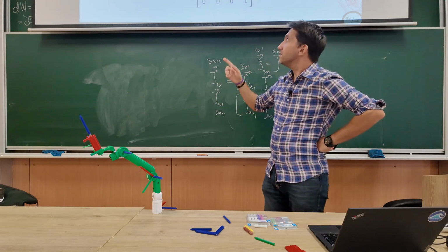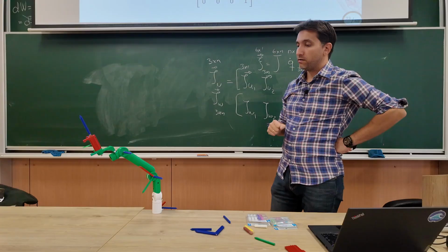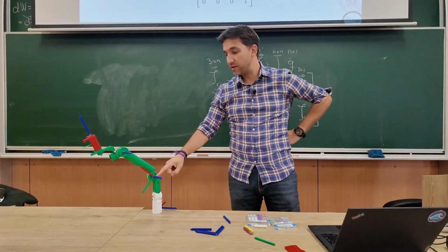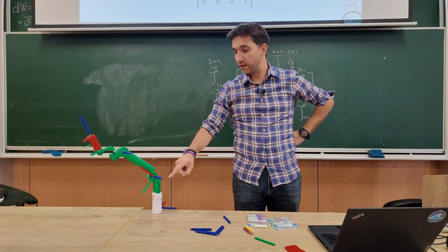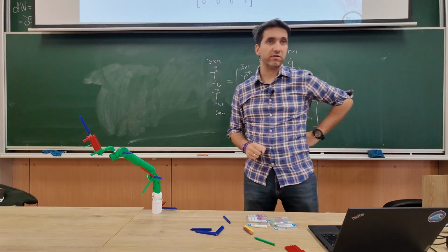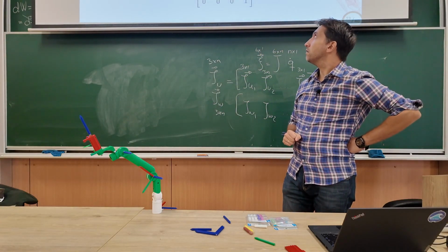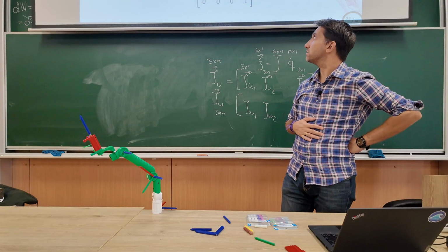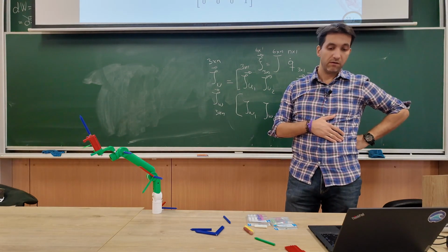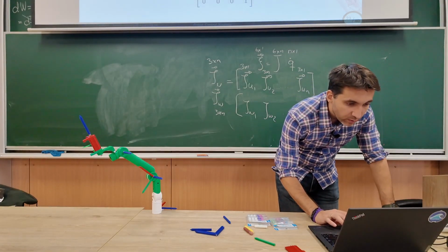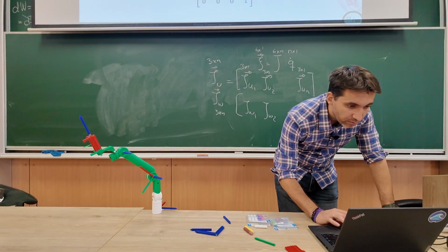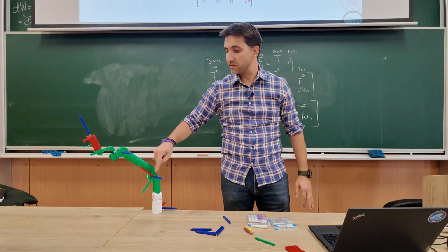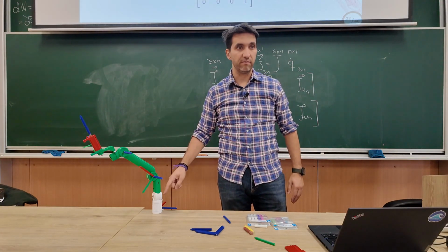Which part would be this vector Zi, which basically gives me the orientation of this vector with respect to the reference frame? Which part from this 4x4 matrix? The third column, right? We saw that this matrix represents the orientation of these three axes with respect to the reference frame.